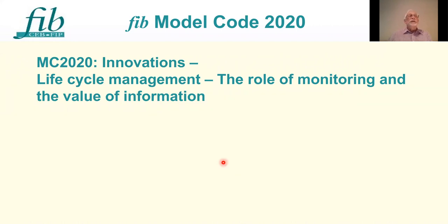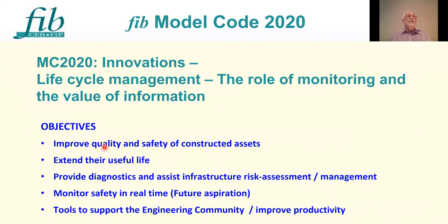Just thinking in terms of life cycle management of an existing structure, there's a role to be played by monitoring and in terms of the value of information gathered. So the objectives of this approach, these techniques, are to improve the quality and safety of the constructed assets being considered, generally to extend their useful service life, provide diagnostics and assist infrastructure risk assessment and management, potentially to monitor safety in real time, and I think that's more of a future aspiration. And of course, these facilities provide better tools to the engineering community.